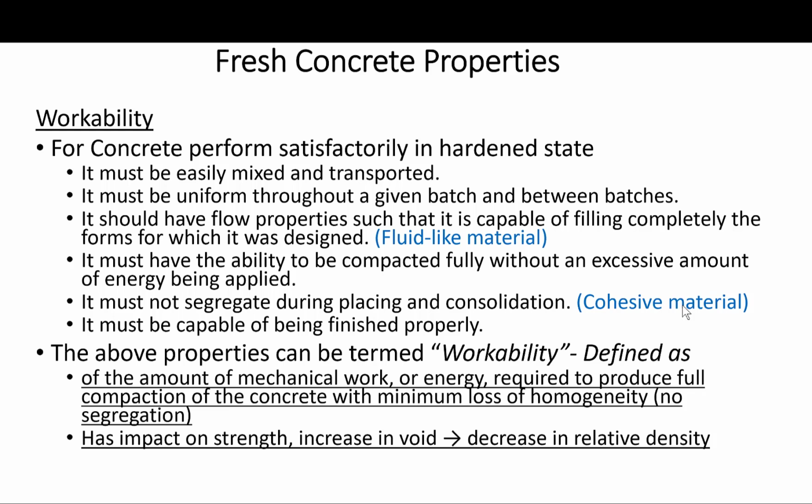Okay, this is a useful definition since the final strength of concrete is in large part a function of the amount of compaction. A small increase in void content or decrease in relative density will lead to a large decrease in strength. If you recall the discussions during the microstructure properties relationship, we talked about how the increase in voids or the decrease in density will decrease the strength.